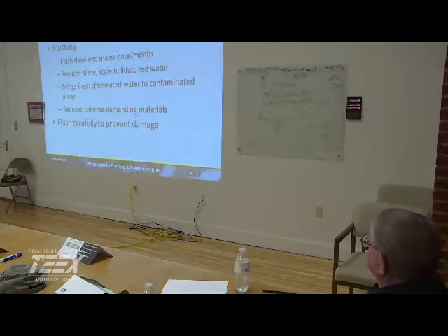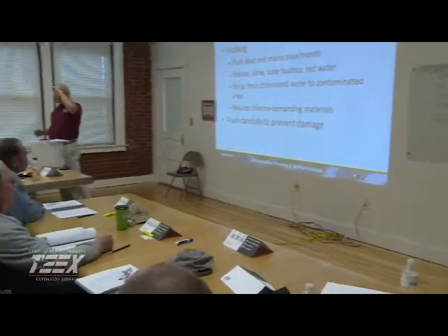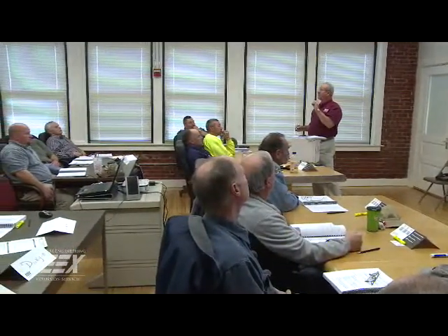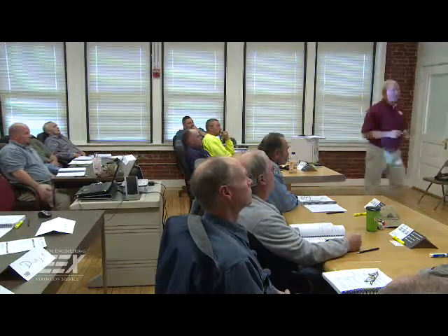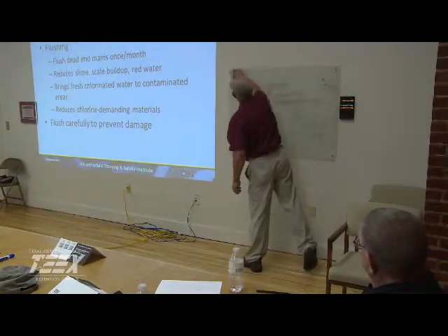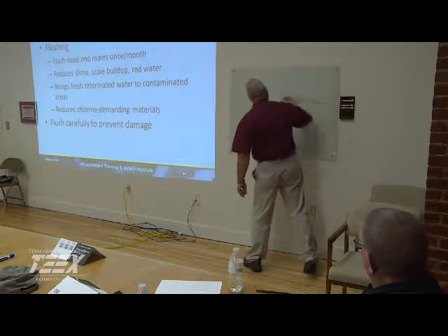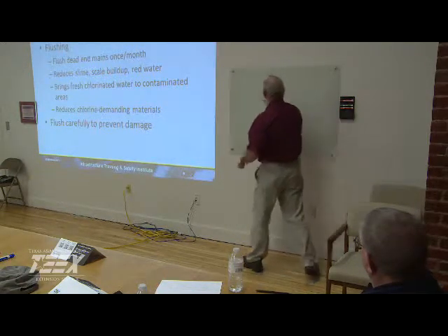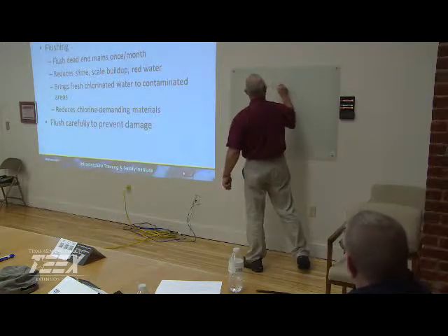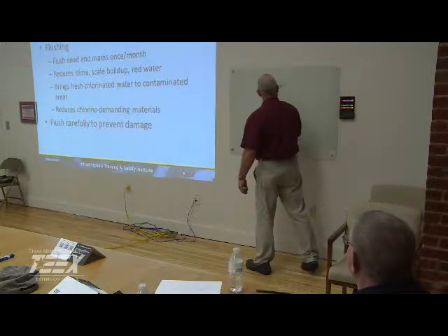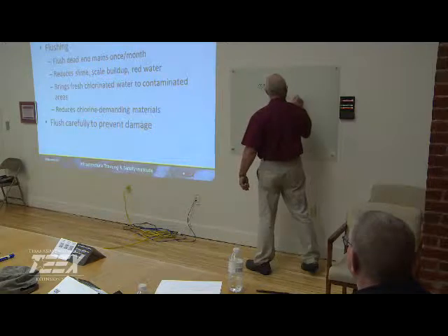Now here's the thing, the AWWA recommends that you use 2 times the volume for flushing at a certain velocity of 3 or 4 feet per second. So let's do that. Okay, so now I've got to flush. Now we know that each 100 feet holds 261 gallons. So I'm going to take 525, divide by 100, times 261 equals.